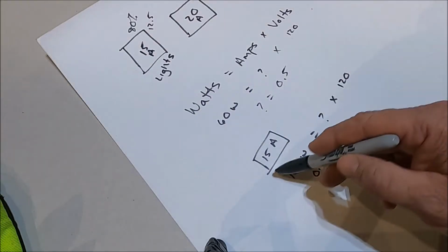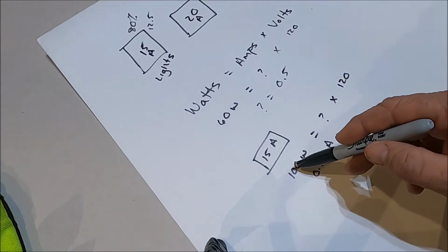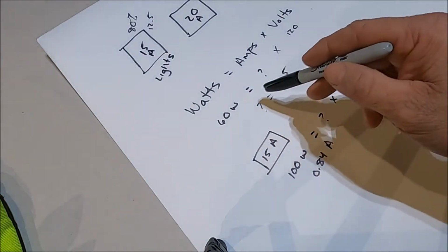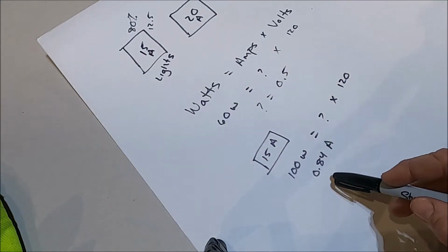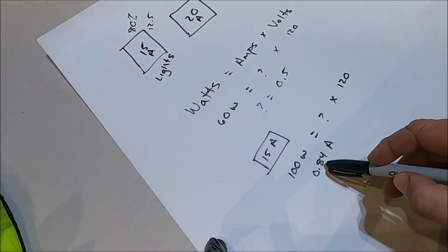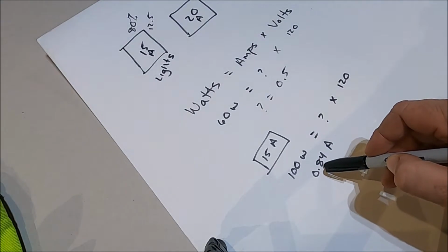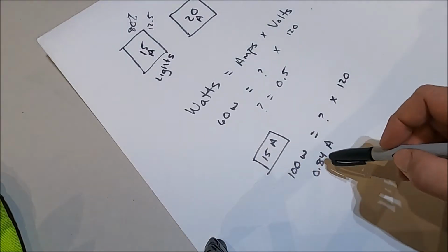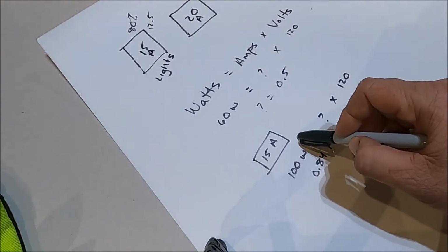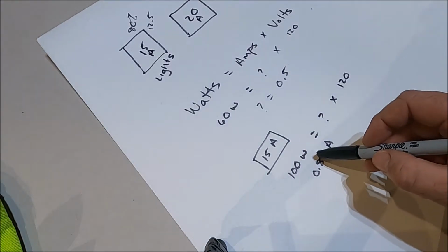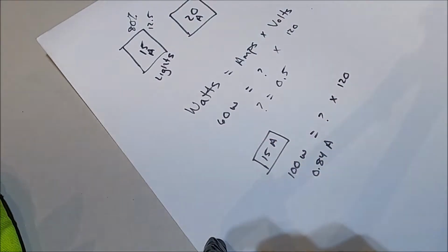So I'm going to have my main lights and a couple outside lights on one circuit, and then all of my side lights that I have under those beams that I made are all going to be on another circuit. So I'm going to have about 6 of these fixtures on the first, so I'm going to be well within my 15 amp breaker here. And then I'm going to have another 8 or so on this other circuit. So I'll still be well within the amperage of this breaker.